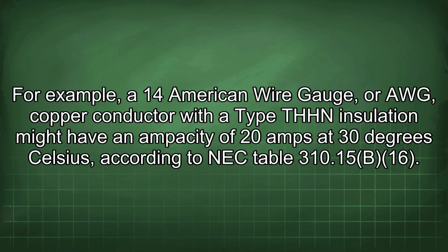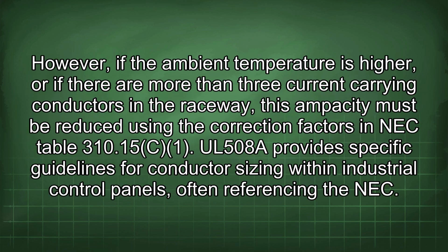have an ampacity of 20 amps at 30 degrees Celsius, according to NEC Table 310.15(B)(16). However, if the ambient temperature is higher, or if there are more than 3 current-carrying conductors in the raceway, this ampacity must be reduced using the correction factors in NEC Table 310.15(C)(1).